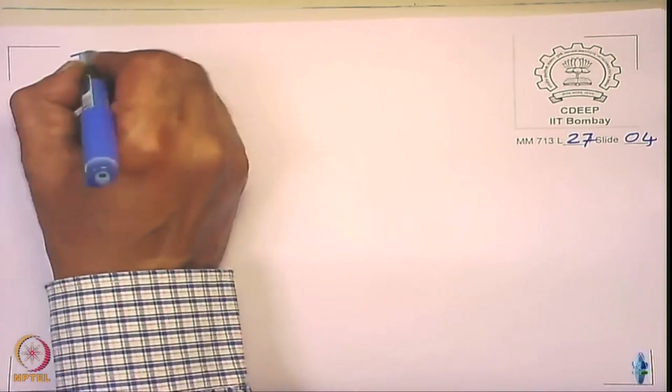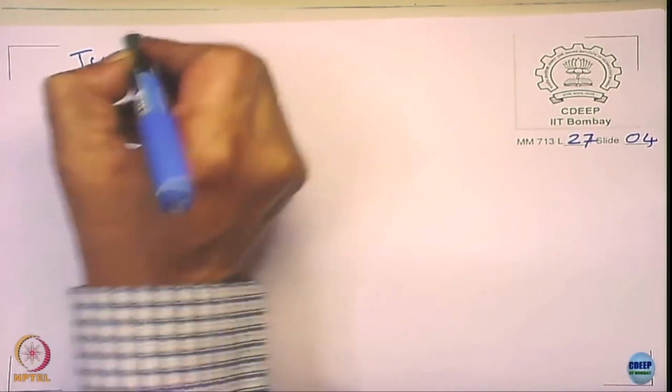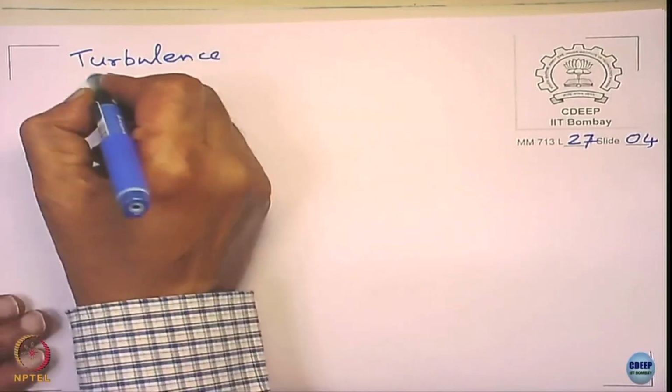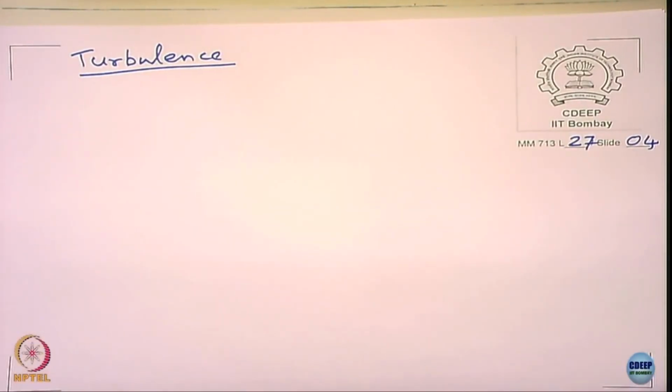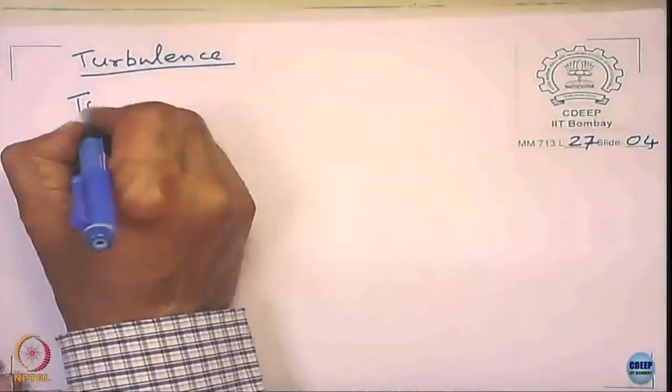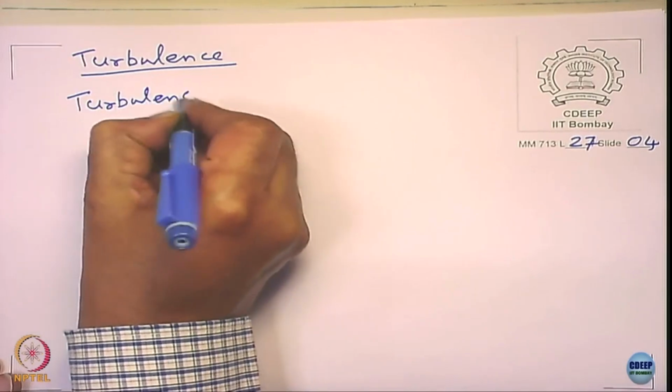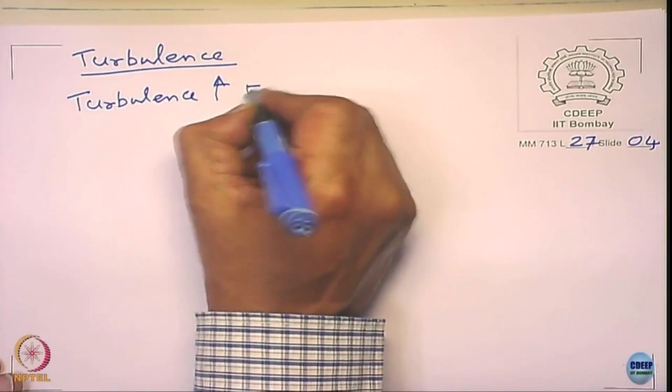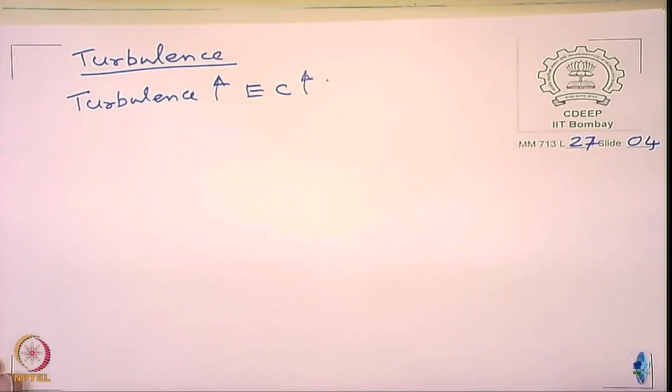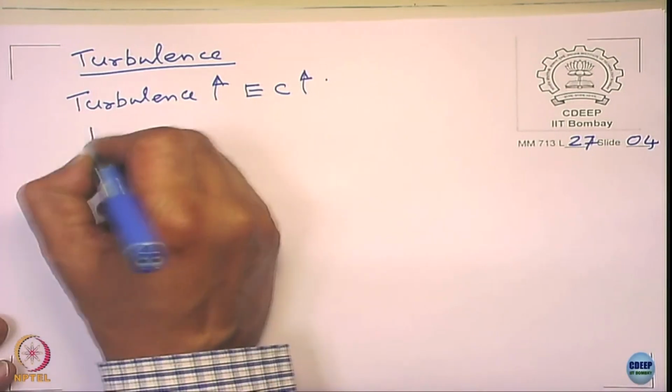The next thing that we talk about is the turbulence. Now the turbulence can happen if the surface is not smooth, if there is a change of direction, or if there is reduction in the diameter of the pipeline. So, higher the turbulence, higher is the erosion corrosion. This is very predominant in the heat exchangers.